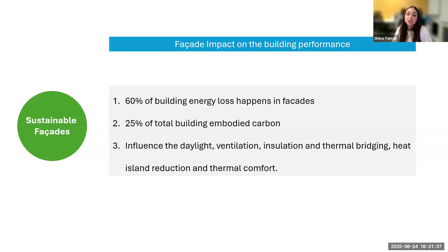On top of that, the facade contributes about 25% of the building's total embodied carbon. So the materials we choose and how we put them together really matter for sustainability. But it's not just about energy and carbon. The facade also controls daylight, ventilation, insulation, and thermal bridging, and it helps keep occupants comfortable while reducing the urban heat island effect. And here in the Gulf,